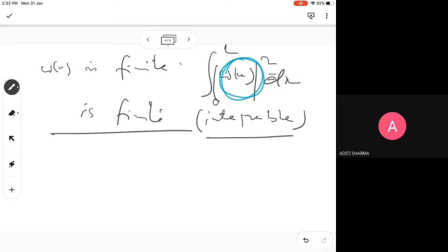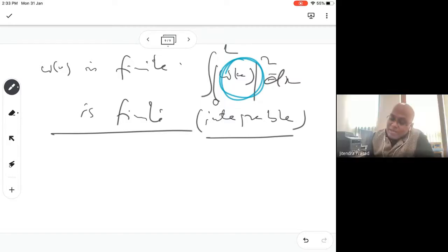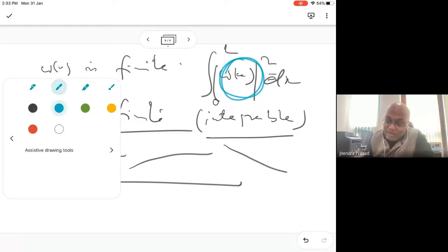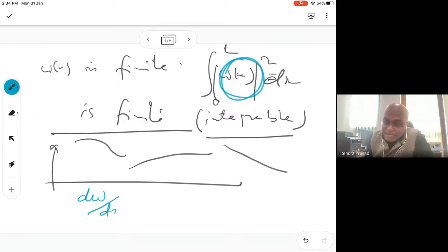Sir, can we have like a rough edge also in between, like two different functions over different domains within 0 to L? Yeah, it could be discontinuous, right? It could be from here to here, and here to here. Jumps are possible then. Yes, with all possibilities. As far as W is concerned. But in the weak formulation, however, we look at the dw over dx term. So in that case, there will be a problem here.